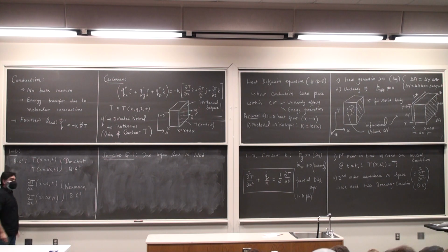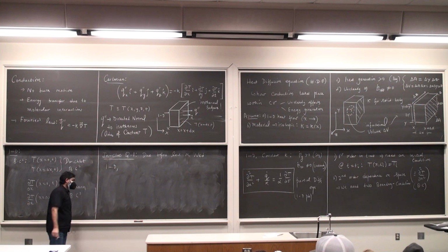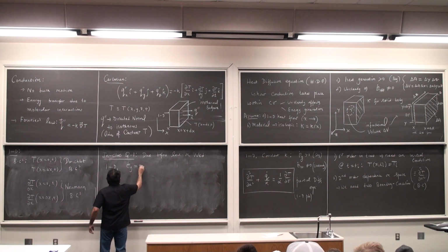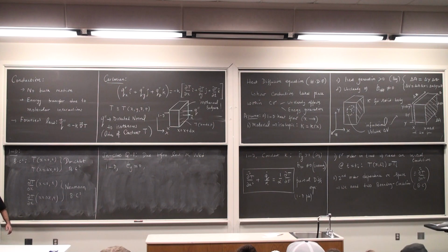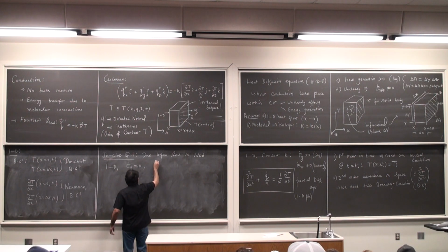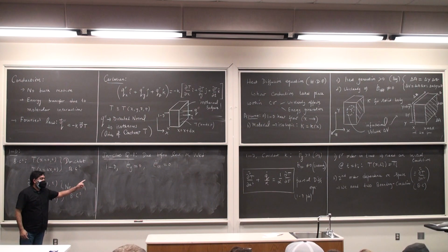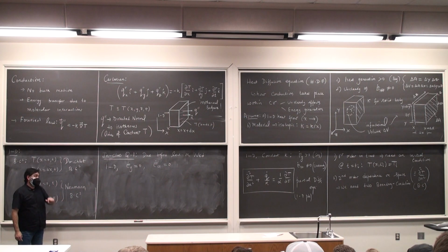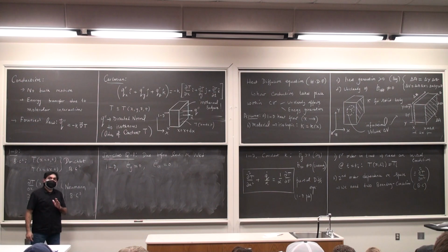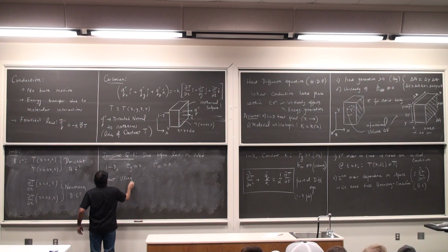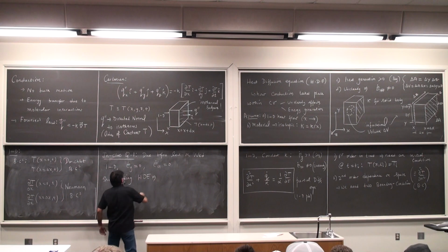Let us assume the following situation. 1D, no heat generation, steady situation. If I have a situation of this sort, what do you think the temperature profile is going to be through the body? Linear. All you have to do, very simple, very trivial, take the heat diffusion equation, then the temperature profile is linear.